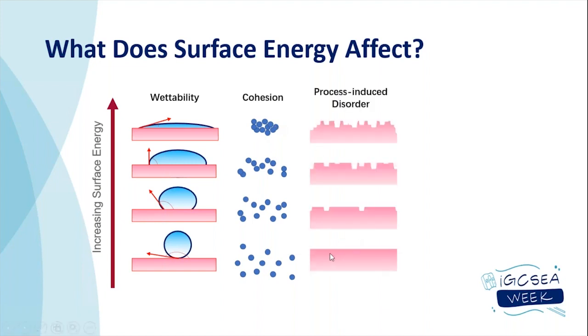If I am milling or grinding or plasma treating or doing some sort of mechanical or oxidative or some other process, very often, although I may make the surface more rough, and surface energy by itself is independent of roughness or surface area, I'm often going to expose buried interfaces, open up different crystal planes, make the surface amorphous, and I very often will increase the surface energy of the material as well.